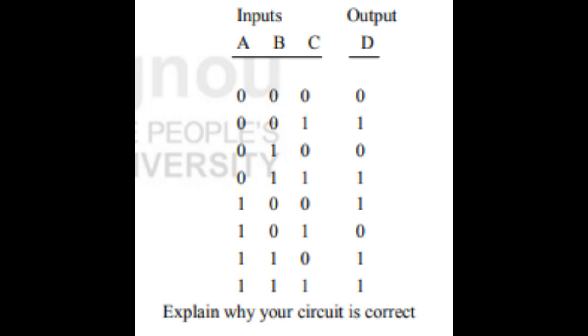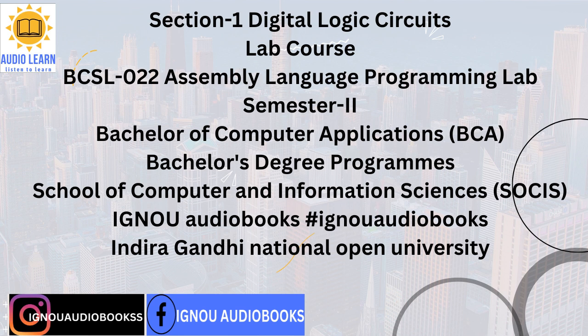15. A multiplexer circuit accepts n inputs and outputs the value of one of those inputs. The selection of which input goes out on the output is determined by a set of m control inputs. A multiplexer with m control inputs can steer up to 2^m inputs to a single output. Design a 4-to-1 multiplexer.